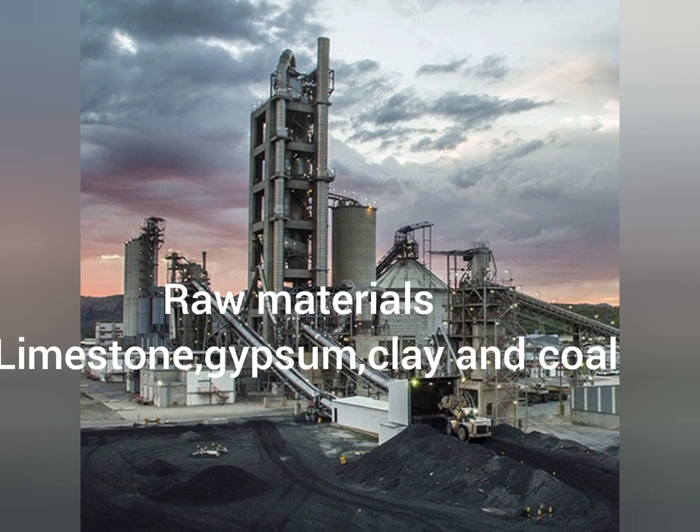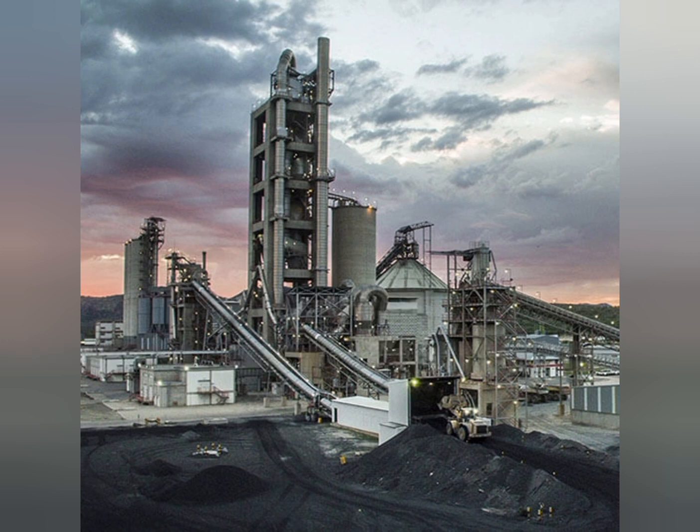The raw materials required for the cement industry are limestone, gypsum, clay and coal. All these are bulky commodities, that is why it's a heavy industry. Tons of limestone are required for cement production. But in recent years, slag from steel plants is also used as a substitute for limestone. Slag is the molten liquid left after the extraction of steel, with impurities of silicates and oxides, and it is used as a substitute for limestone in the cement industry.